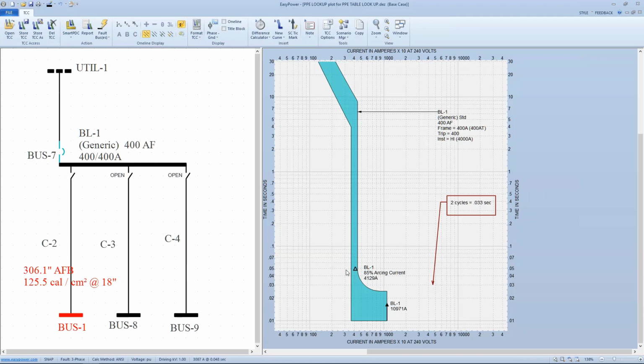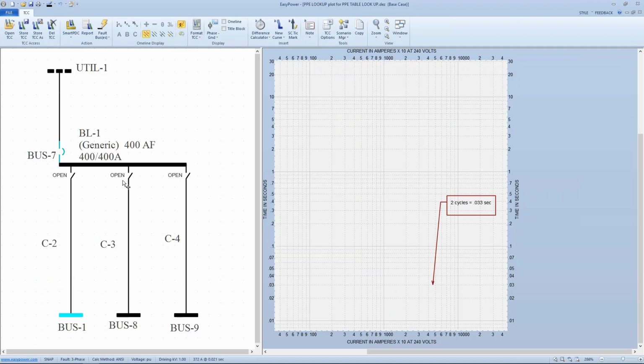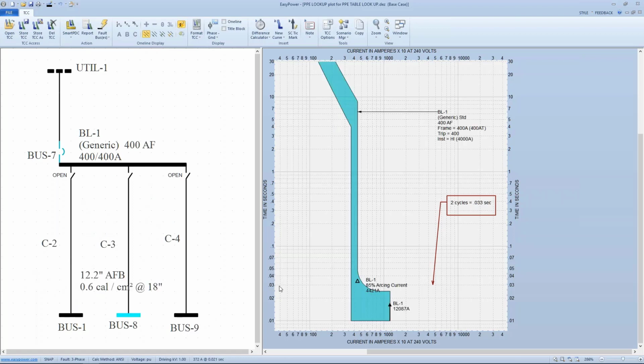4,000 amps is on the hairy edge of being non-self-sustaining, but according to studies, it still has the potential for sustaining for as many as 3 or 4 cycles. So that brings us to the point of what is the minimum amount of current at a fault that would guarantee that we fall into the instantaneous range on that trip curve.